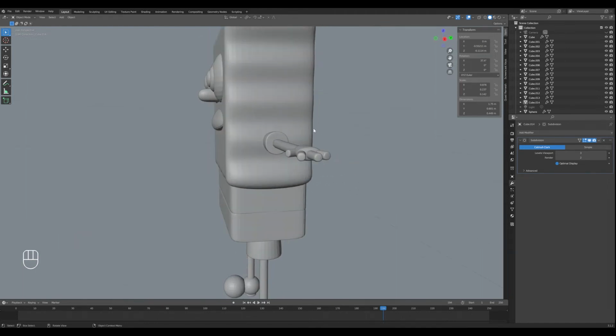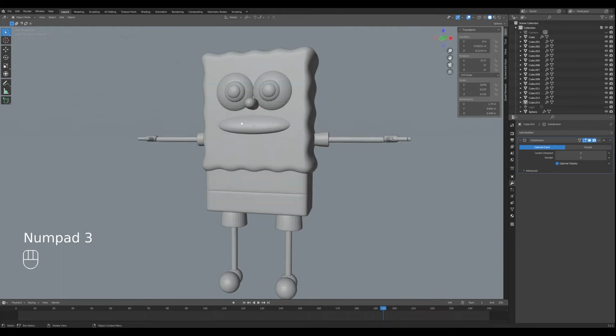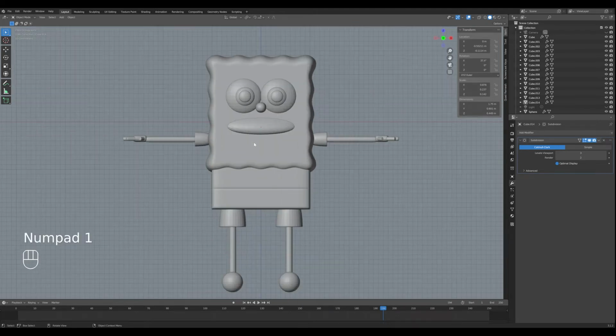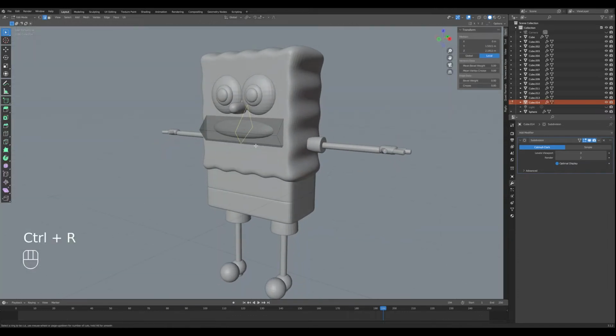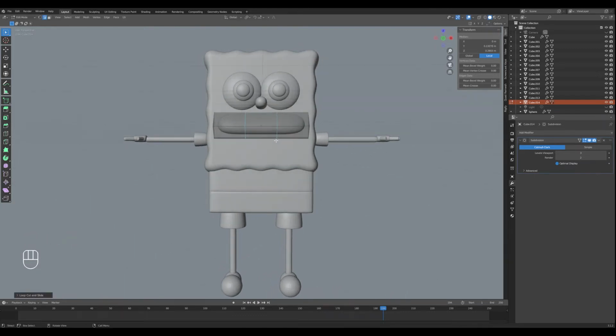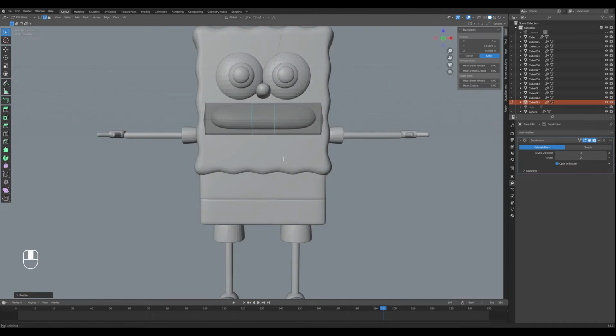Yeah. You see what we're going for though? So here's the top lip. There's going to be teeth underneath. So this way we can click the mouth, click the body, and then we'll join it here in a little bit. Let's see, it should be more curved for his smile. So let's go into edit mode, add some loop cuts. I'm going to add 2. And then we're going to scale them along the X-axis a little closer like this here.